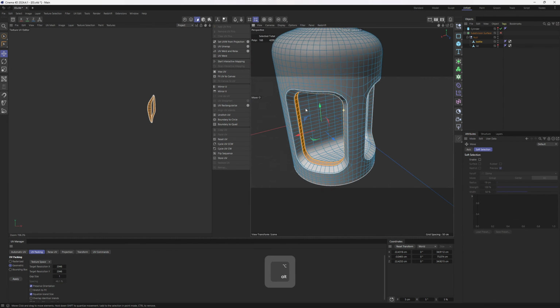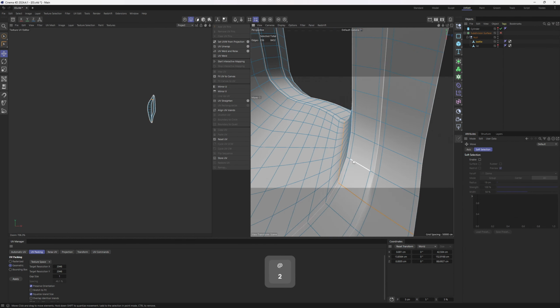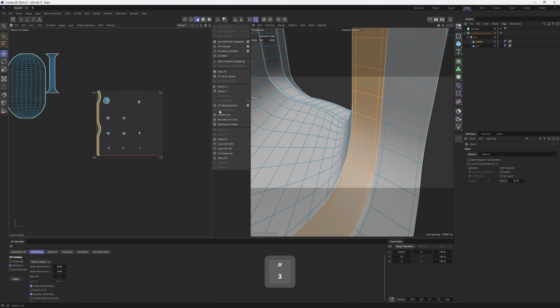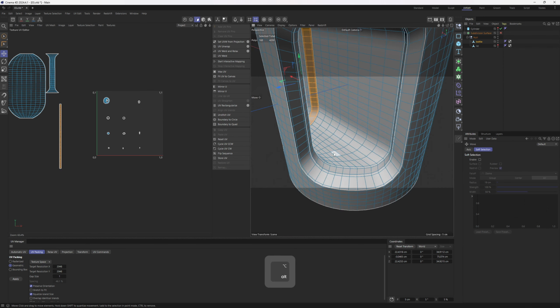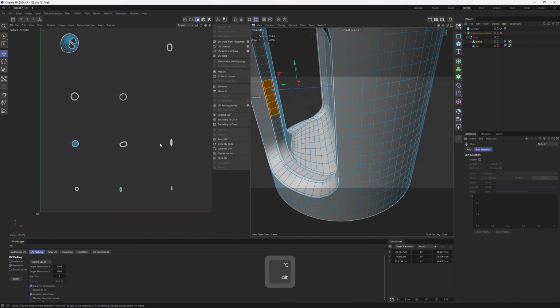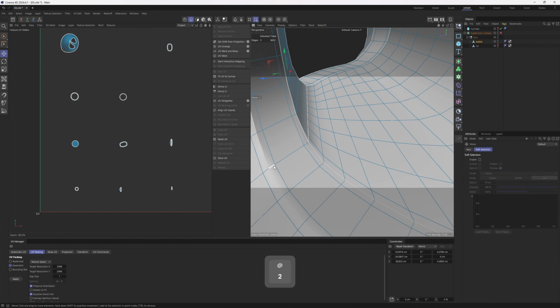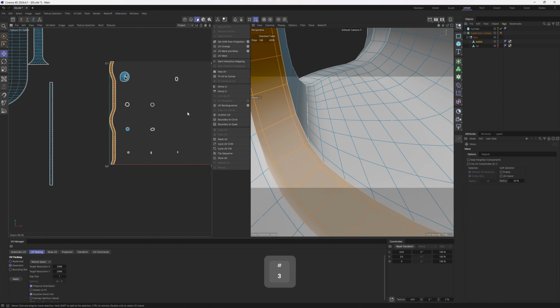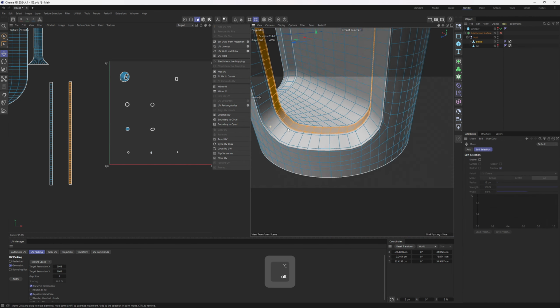weird looking one like this one. You know what to do. Just select these edges, then click on UV Unwrap. Then I will apply UV Rectangularize tool. Move this off. Next up, this one. Double click first. Select the edges, UV Unwrap, UV Rectangularize, move off.